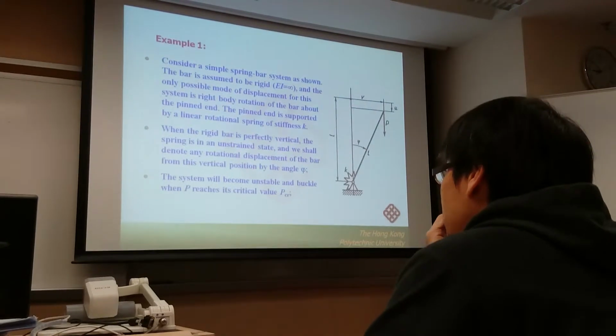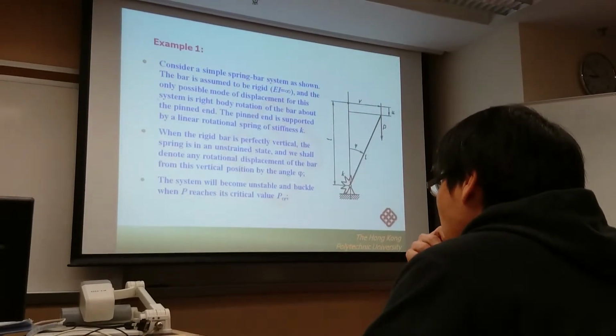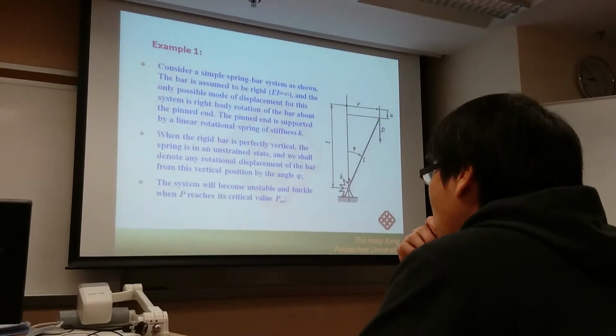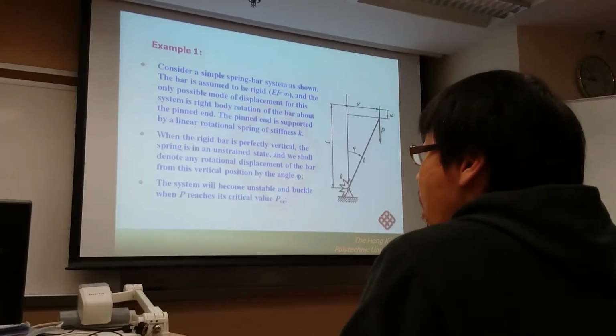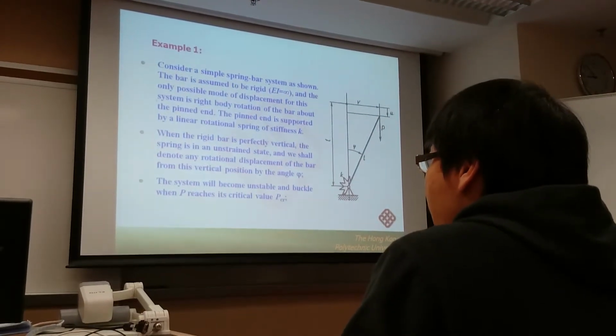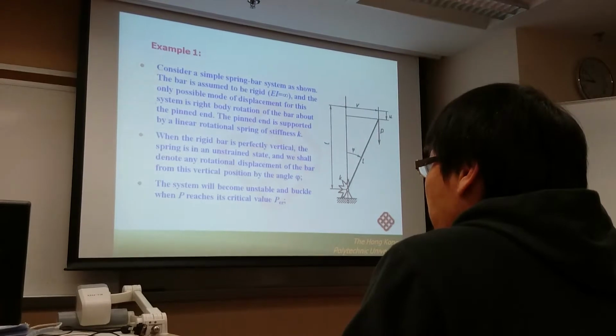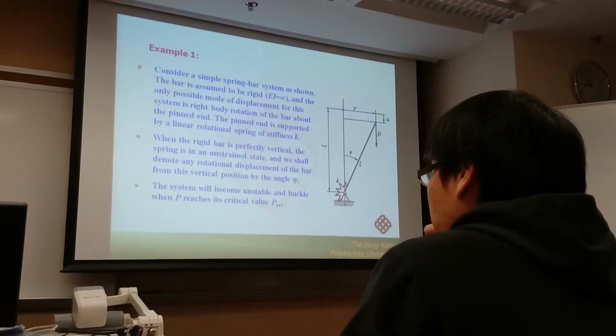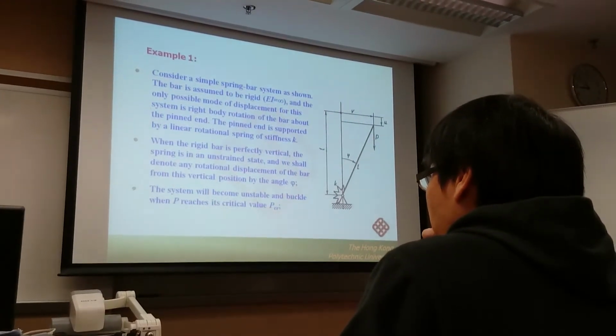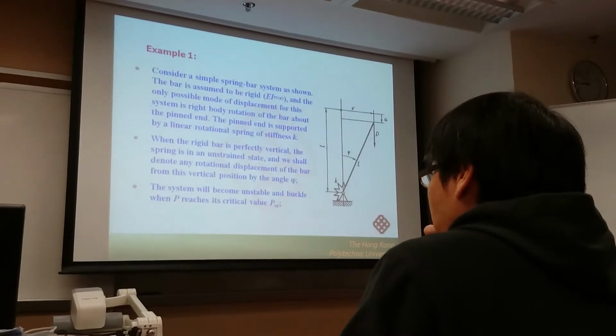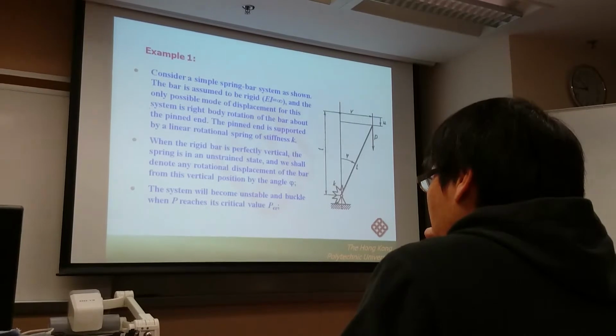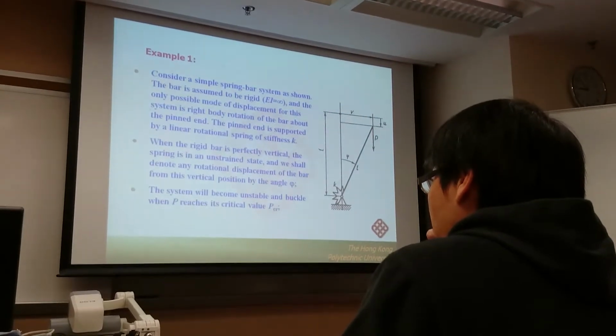The structural response is always equal to 0. If this is an elastic member, the response is vertical deflection. It is impossible to have a horizontal response because the force is vertical and the column is also vertical. So horizontal response occurs only when buckling occurs.